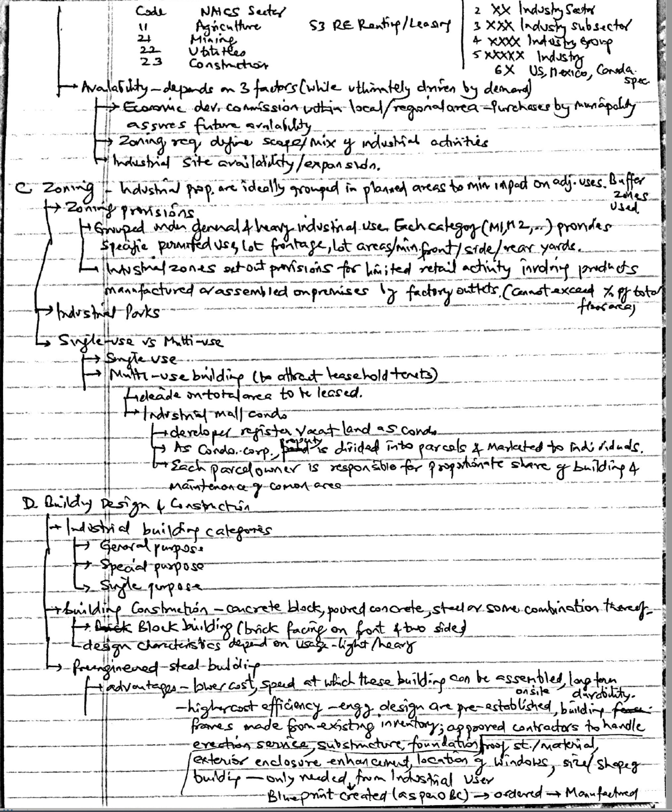Prospective buyers must evaluate costs associated with substantial modification required to accommodate alternate uses. Given that industrial structures are process-intensive, improvements can be particularly vulnerable to obsolescence. Ceiling heights, clear spans, floor loads, etc. from only decades ago can render a building obsolete by today's standards.